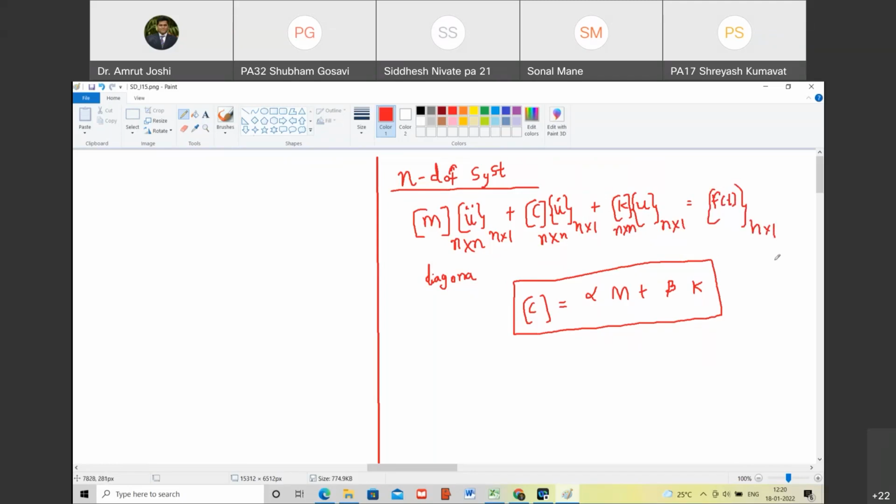So in the next class, naturally, we are going to look at forced vibration problems. Are you with me? And here, resonance has a different connotation. Resonance will occur when the forcing frequency becomes equal to omega 1 or omega 2 or omega n. So यहाँ पे n number of frequencies will correspond to resonance. Are you with me? Yes, sir.